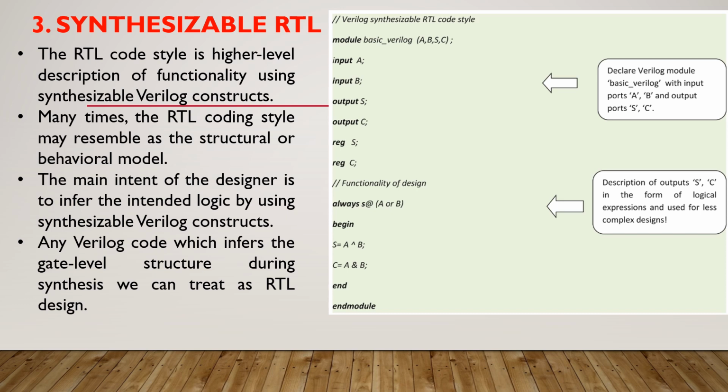Many times, if you look at RTL coding, it may resemble a structural or behavioral model only. Actually, after writing the program, you want to create the gate level netlist. That is our main objective.